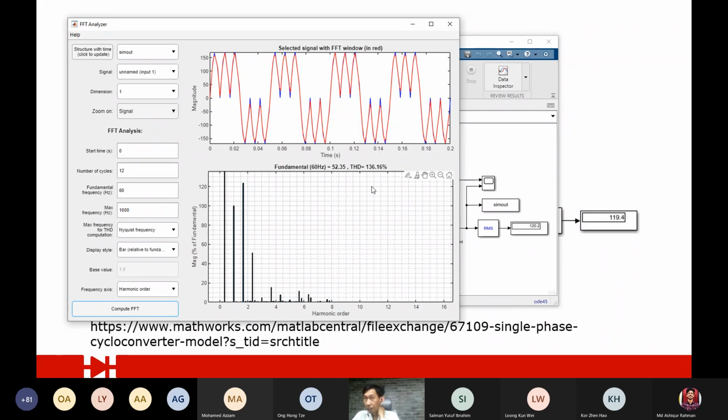It's just like the transistor we are using. When we operate a transistor at very high current, we know it's going to heat up. Then what you need to do is design a proper heat sink to help dissipate the heat, because there's nothing else you can do. The heat can sometimes go up to 100 degrees Celsius, high enough to boil water. But if you operate the same transistor at very low current, you don't even need a heat sink. As simple as that.